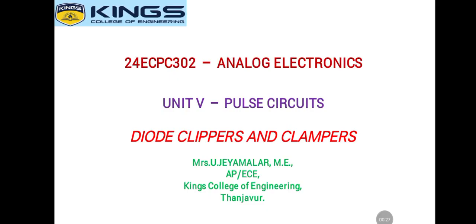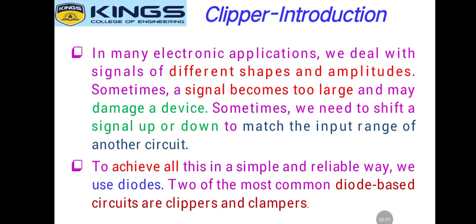Introduction about clippers. In many electronic applications, we deal with signals of different shapes and amplitudes. Sometimes a signal becomes too large and may damage a device. Sometimes we need to shift a signal up or down to match the input range of another circuit. To achieve all this in a simple and reliable way, we use diodes. Two of the most common diode based circuits are clippers and clampers.